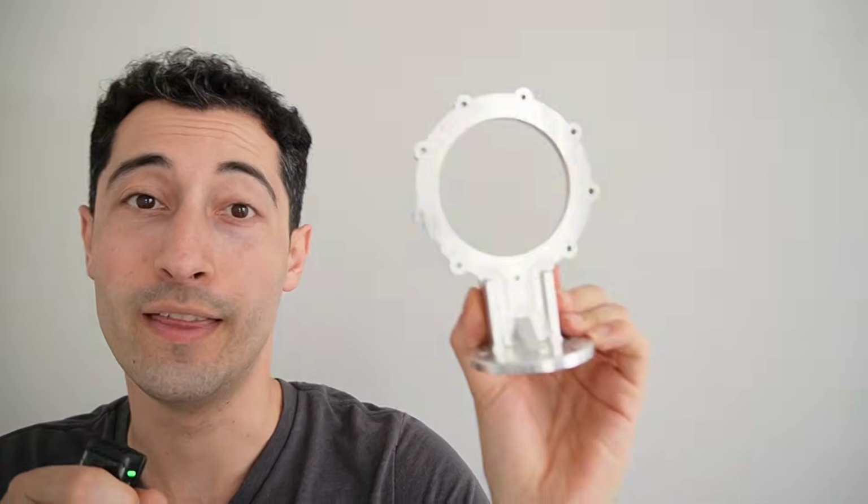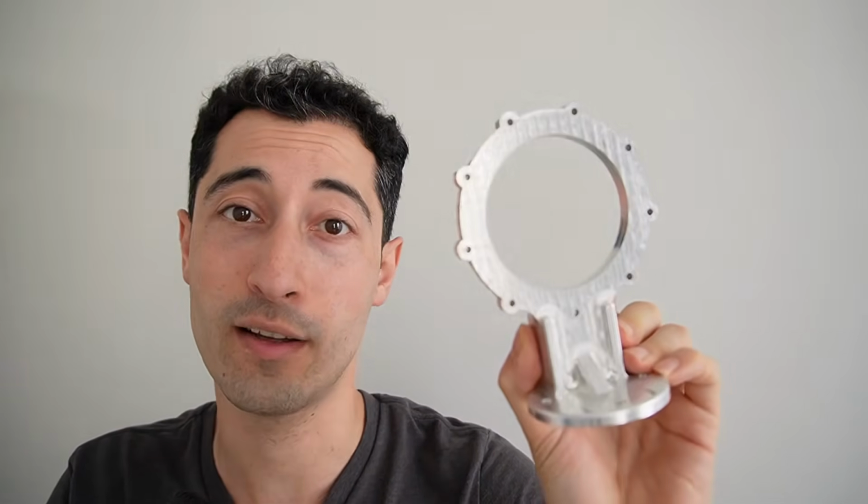So we're going to have to change the material. This bracket is made of nylon 6. It vibrates at about 130 Hz, so a little bit different than the motor, but even though this is much stiffer and better, it still is having some issues in simulation. So we're going to have to bring out the big guns. This bracket is machined out of aluminum. It has a frequency of about 400 Hz, which is very different than the motor frequency. So we're not going to experience a lot of the same issues with this bracket.